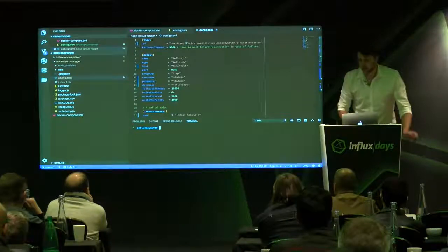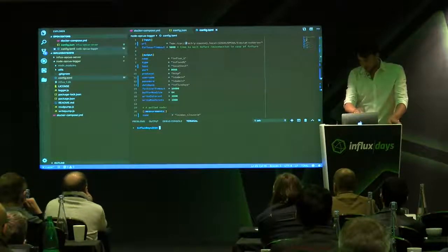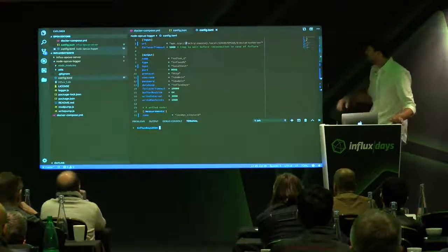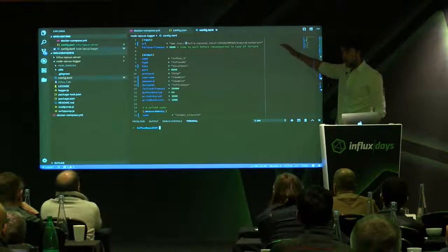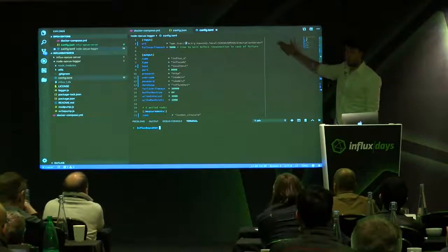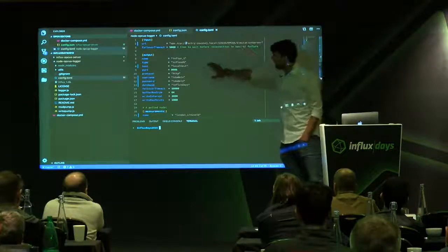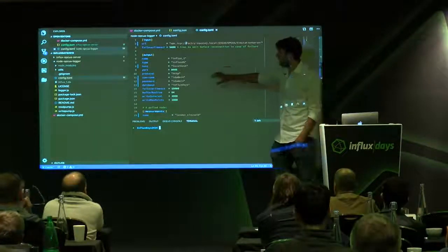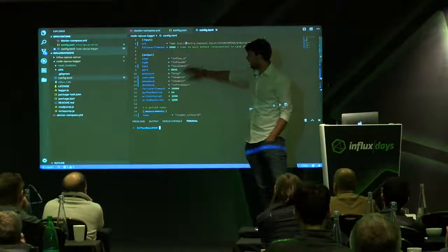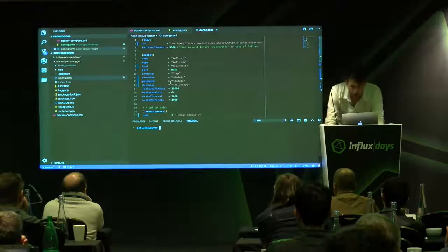So you download the logger, and then you can create a config file. You put in the endpoint of your OPC-UA server. In this case, there's no security, so I don't need to worry about that. That's your input. Then your output, your Influx database. Mine is running on localhost. I have 2 Dockers running.